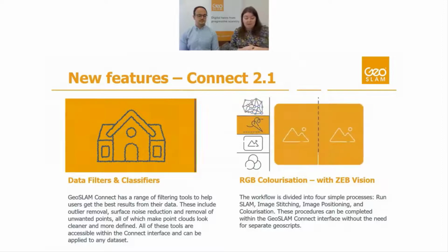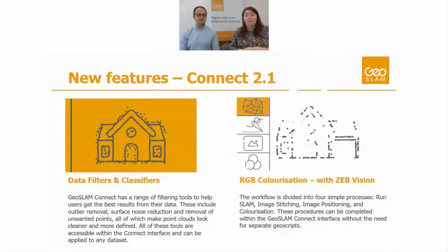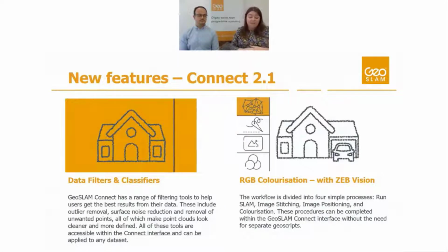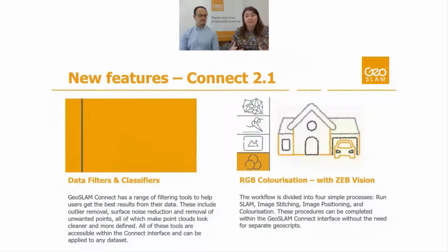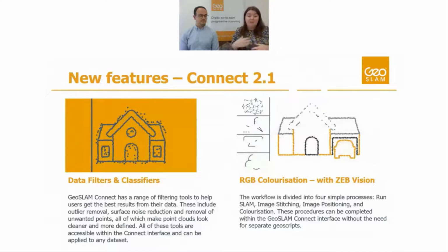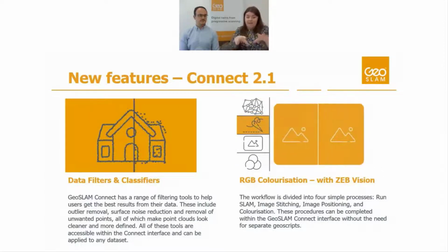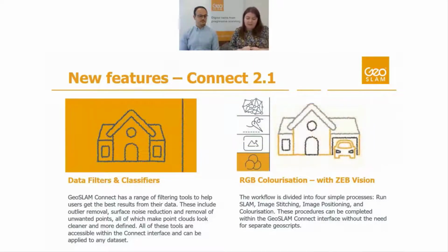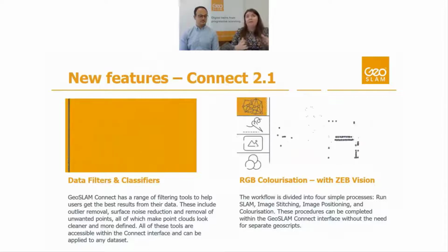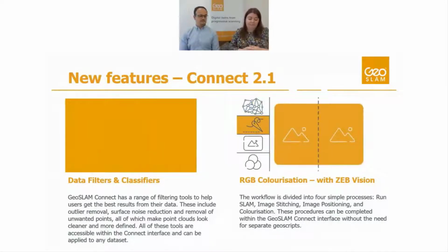We've then got a range filter as well. For our horizon scanner in particular, it collects up to 100 meters of data, so this really limits that view. If you're scanning in indoor environments and you obviously don't need 100 meters, or if you're outside and you're only really interested in the area immediately around you, you can limit that range, and this is along the trajectory. So it's X many meters from your trajectory.